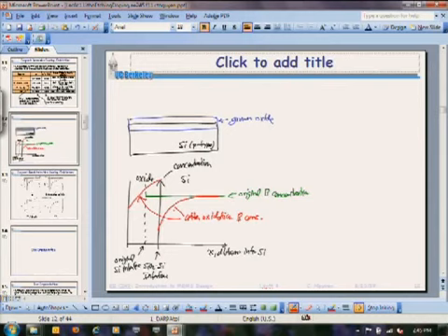So in your homework problem, you have not only boron in your silicon, but you've got some other dopants too. Those problems are there to say, if this boron is depleting from the surface, doesn't that mean that whatever other dopant I have in here, depending on what it does as that oxide grows, can now dominate the doping concentration at the surface? The answer is yes, it can.